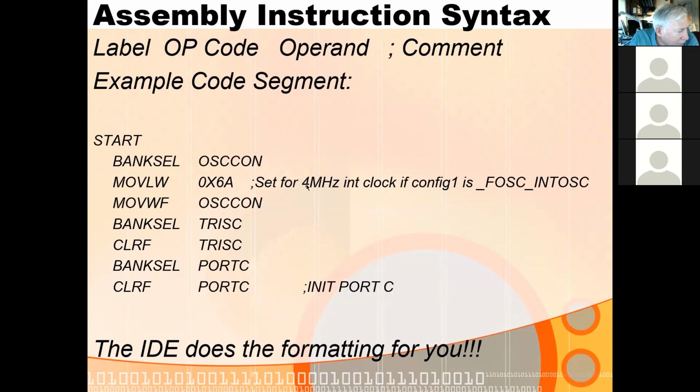And that just kind of gets things set up, ready to go. The IDE will format these things for you. And then the last field is your comment field. If you want to have a comment, you don't do //, you use a semicolon. A little kind of crazy. I know, C uses the semicolon to be the end of the instruction.